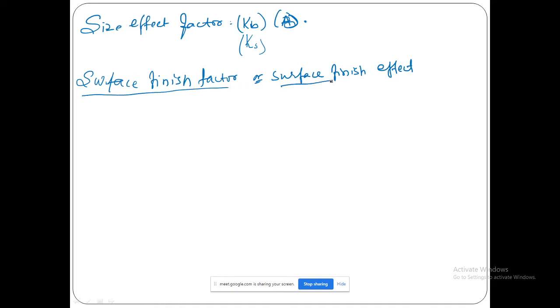In relation to the specimen preferred, the beam specimen for conducting the experiments is of mirror finish nature. The purpose of surface finish is to remove any scratches or indentations over the specimen. If it has any surface scratches or imperfections, they have to be removed before conducting the experiment.